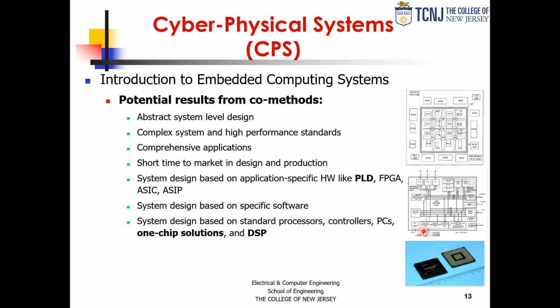That's system in a package and is allowing more integration of functionality per actual size of real estate. So why don't we make a big chip? Because remember the yield, because of the intrinsic defects in, let's say, silicon, if that's the technology and the process that you are using, there's nothing you can do about the intrinsic defects in the material. So the yield, percentage-wise, is directly related to the size. So you get better yield with smaller chips, in fact.